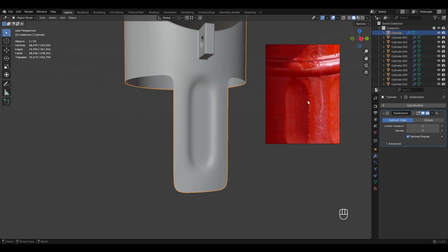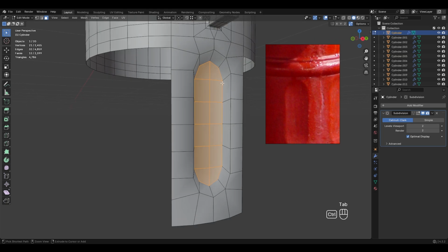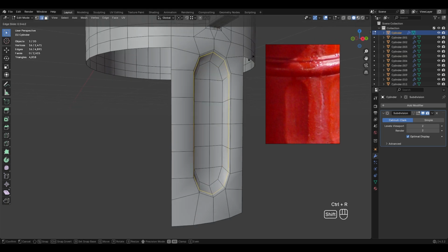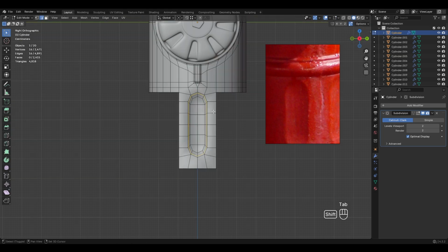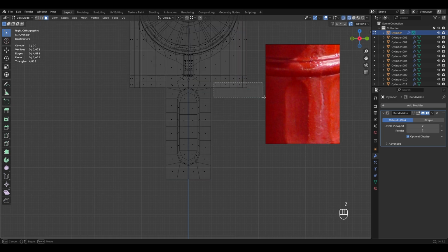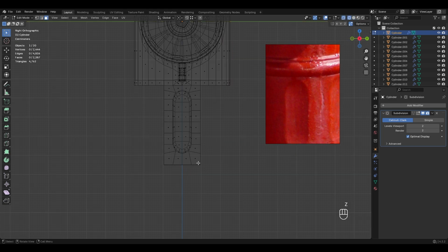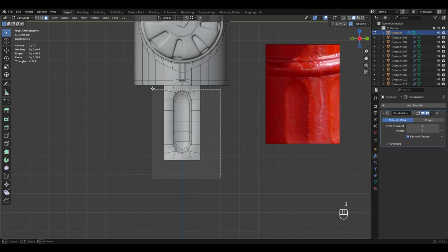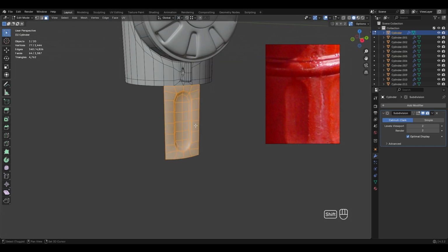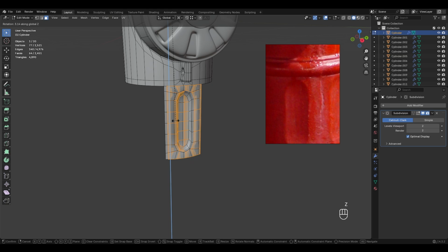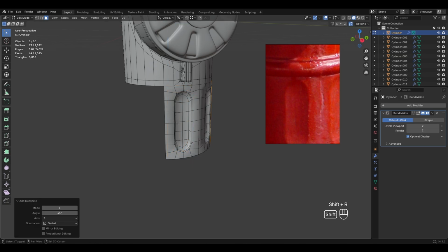This outer part is a little sharper. We need to make it sharp. So here we need to add an edge loop maybe from here. So we need to make a copy. Also, we need to delete this part and then select these and put this on 3D cursor, Shift D, R, Z, and 45. And press Shift R to achieve that.